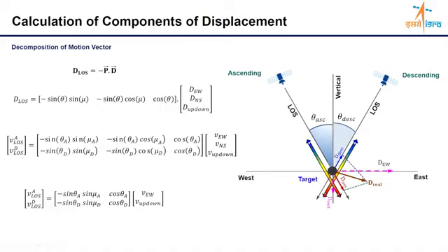It means the P vector is also known. Just keep in mind, we have drawn this from the InSAR application. So these three components are known, and what is unknown? The east-west component of the displacement vector is unknown, and the other two are also unknown. These are our interest, the three components we want to investigate.